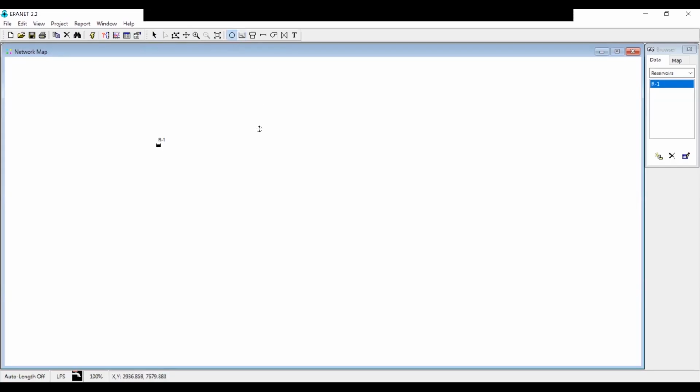And we will add our junctions. Junction 2 is here. Junction 3 here. But their label is changed because reservoir is a node as well. These are nodes, but junctions, node is the general name of all these. These are junctions. This is a node as well, but this is a reservoir. So the number increment is because of that. I want to use the same numbers which are seen in the handout. So I will arrange them later.